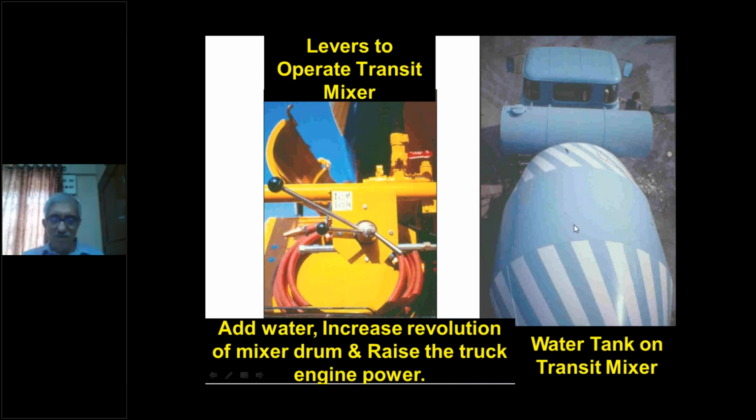Now, when you add too much admixture, it behaves like chloroform on a human being, and automatically the concrete goes to sleep and does not revive for 6 to 7 days at times, causing a problem at the site. So it is recommended that this addition should be very strictly supervised and not left to the driver and the cleaner of the transit mixer.